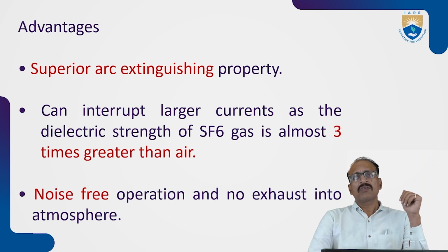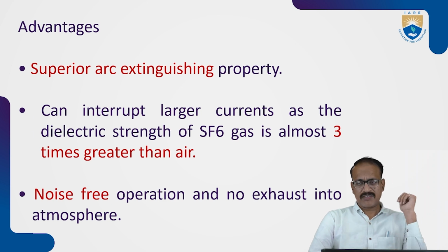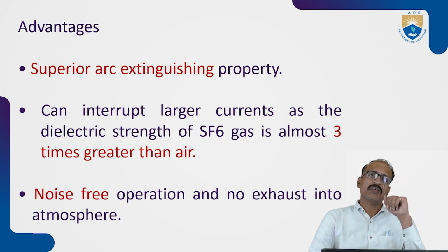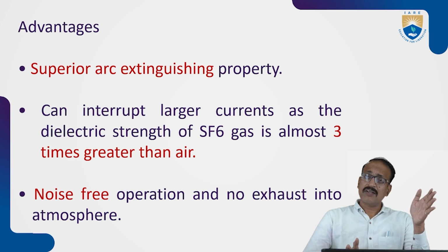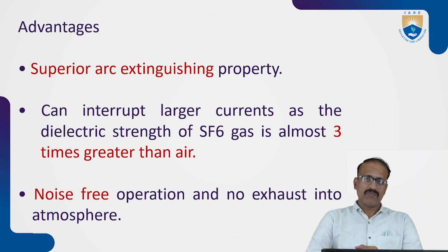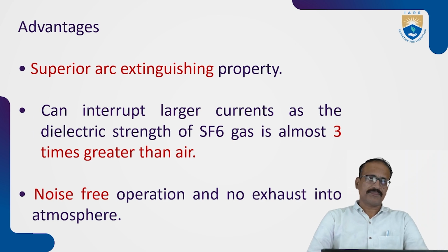Even if the arc strikes, this dielectric strength helps in reducing it. On one side it has more dielectric strength, and on the other side it is electronegative, so it has the best advantage compared with the previous circuit breakers.